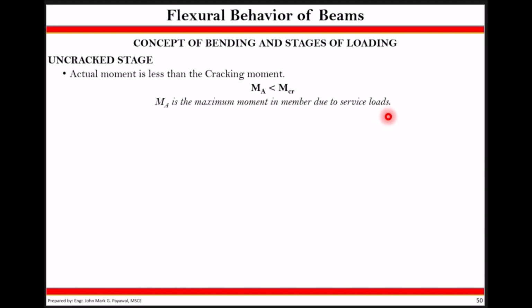So what's your service loads? It could be a combination of your dead load and of your live load. Your dead load could be your self-weight and your superimposed loads: your mechanical ducts, your tiles, your floor systems, everything that could be included on dead load and live load.